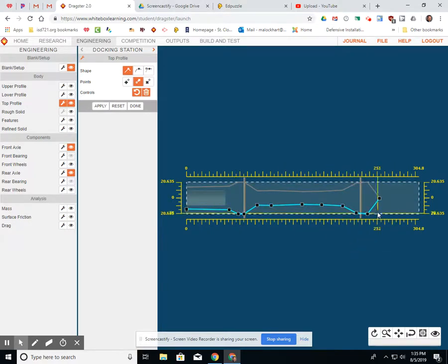That is the width. It tells me that my width is not correct at either axle, and here's the reason what we have. If you take a look at the front axle, see this point right here and see how it's not sitting on that dotted line right above it. That means that this line goes at an angle and that whole axle is not coming through an area on that block of wood that is the correct width. Easy to fix: just make sure you remove your point, grab that dot, pull it down till it's on the dotted line. Once you've pulled it down and it's on the dotted line, you should be okay.